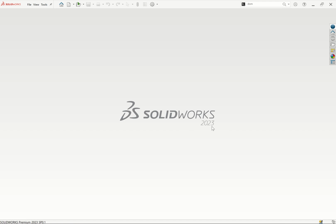Because if somebody has designed the file using maybe 2024, and he or she sends you the file, and you have SolidWorks 23, directly you will not open it unless that person converts that file to either a STEP file or IGS file, depending on the format you want. But the best format I normally use is STEP file, so they're able to open it in all other versions. If you design in a higher version and send the raw file to them, but they have the lower version, they will not be able to open it. But the lower version can be opened in a higher version.